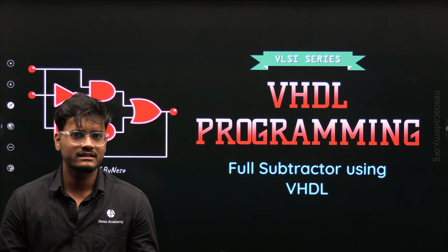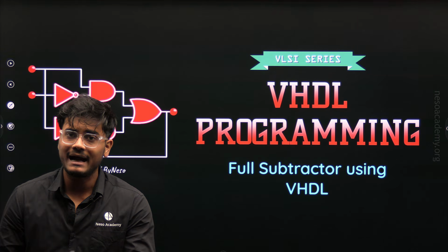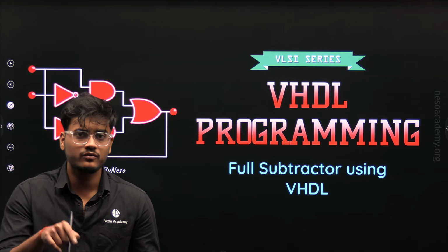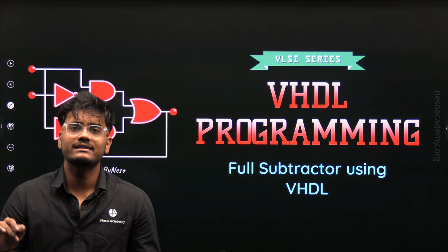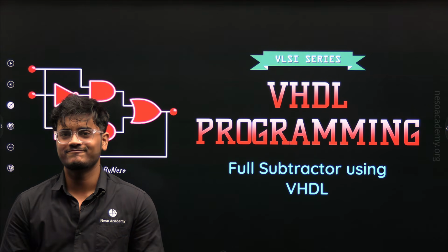But in practical digital systems, we often need to perform multi-bit binary subtraction. And in multi-bit binary subtraction, the borrow generated from one stage must be passed to the next stage. But in half subtractor, there is no input terminal to accept this incoming borrow.